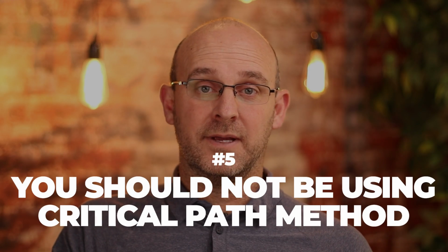Number 5, you should never, ever, ever be using CPM for your overall schedule management. It should always be tact. If you have to export to CPM for some schedule requirement, that's fine, but we do not start to do a forensic analysis of the CPM schedule to make the project go better. We do not care about float trends. We do not care about slippage reports. We do not care about the critical path. We do not care about any aspect of the CPM schedule to manage the project.